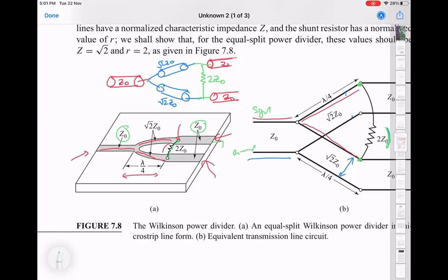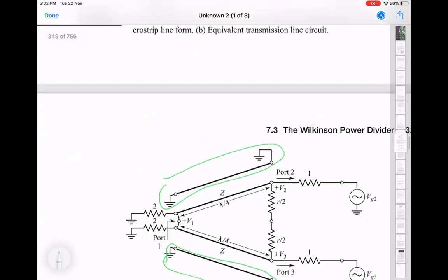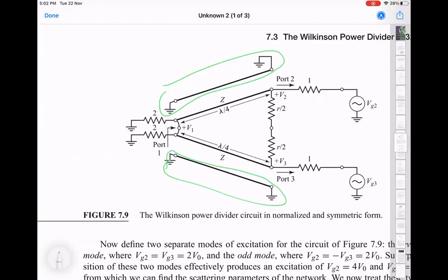So the relevant part really is just this much, right? It has two transmission lines going in this sort of split format with a characteristic impedance 2Z0 and a resistor connected across the two terminals. Everything which comes on either side is a 50 ohm transmission line. Okay. So that's exactly what they have done. So your ports are here. So this is sort of the port location. This one here and this one here. Okay. So you identify the 3 points.